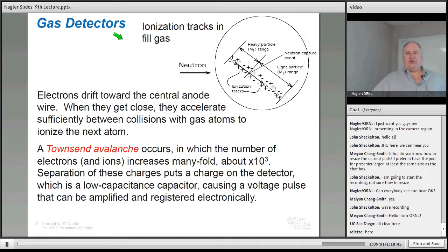Now, I'm oversimplifying things here, but because of this fairly energetic nuclear reaction, this generates a lot of electrons, so I get a certain spectrum of generated voltage that I can look at in a pulse analyzer. And if I have some other thing like a gamma ray that gets in there, it generates fewer electrons and therefore a smaller voltage drop, and I can use electronics to discriminate between them. So this kind of counter, although it's an indirect method of detection, allows one to discriminate between neutrons and, say, gamma rays. That's a fairly important thing.